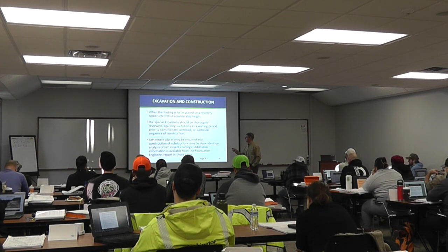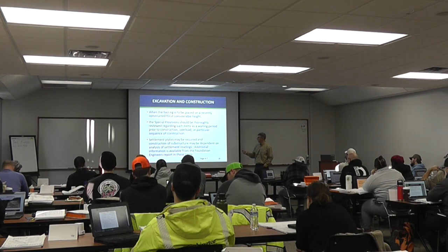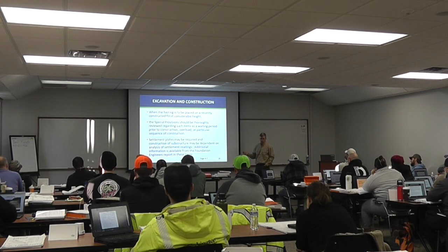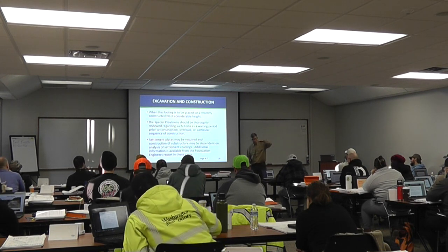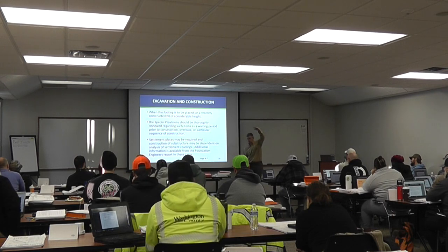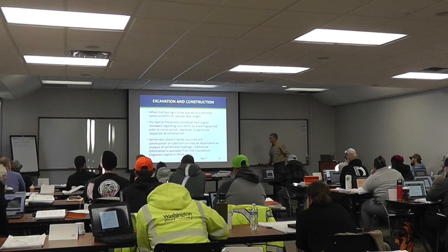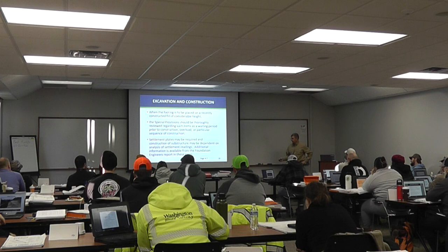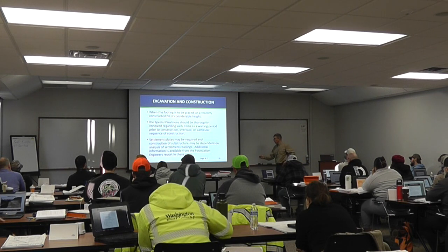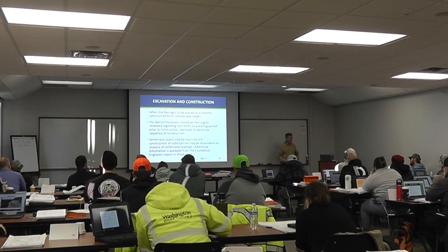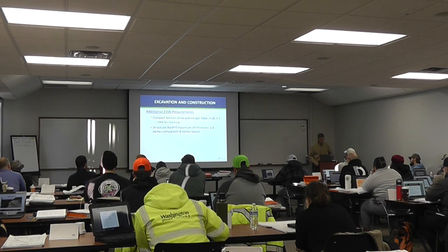So just think, is there a waiting period? Is there any other kind of thing? Do we actually have to build not only to full height, but surcharge it some additional? So be aware of what you have. And then settlement plates might be required, and we spoke a little bit about that, depending on what we need for our settlement.